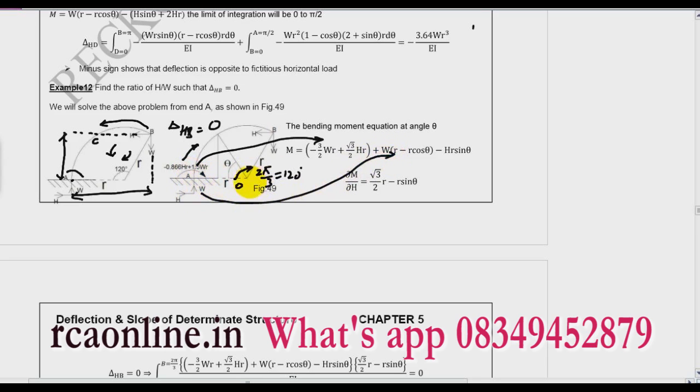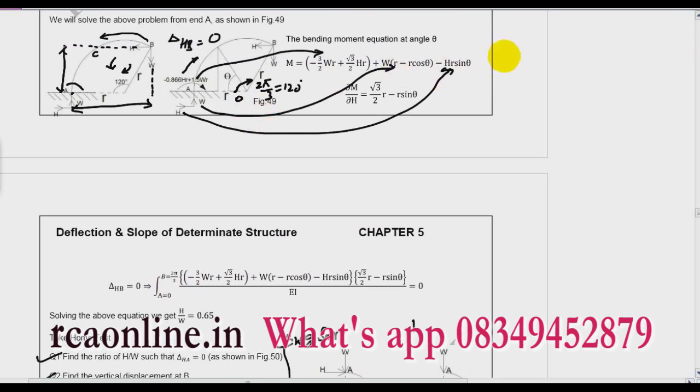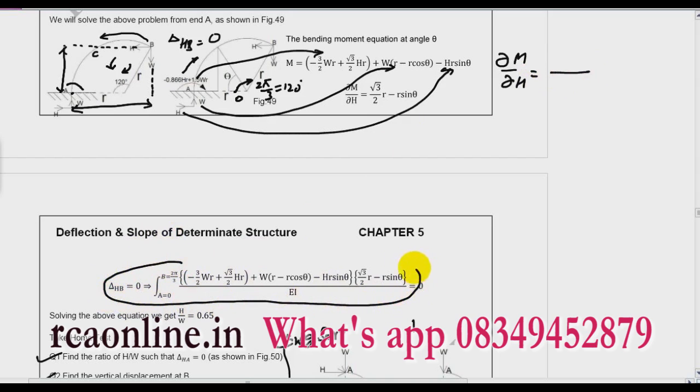So what is my lever arm? It will be R minus R cos theta. And what is my horizontal lever arm at this point? It will be H into R sin theta. When you put the value and make the integration for delta HB, what you have to do is differentiate del M by del H. Put del M by del H equal to 0. So this whole expression will be 0, and when you solve, what you will get? You will get H by W is equal to 0.65.